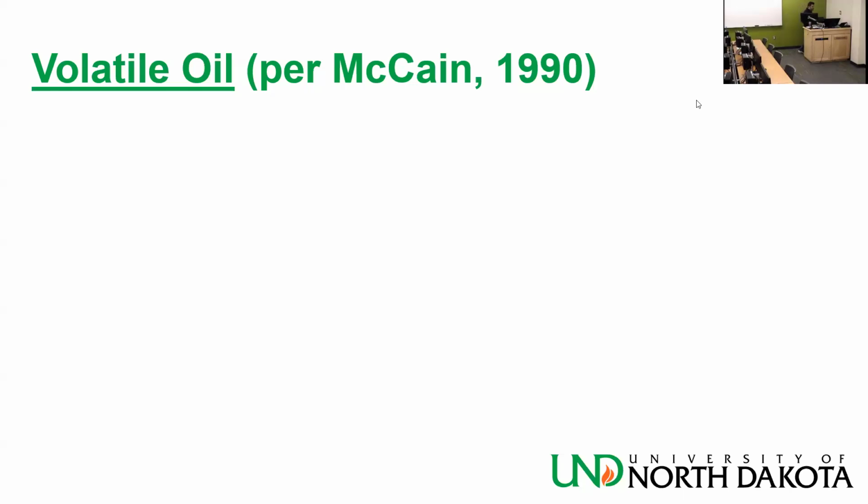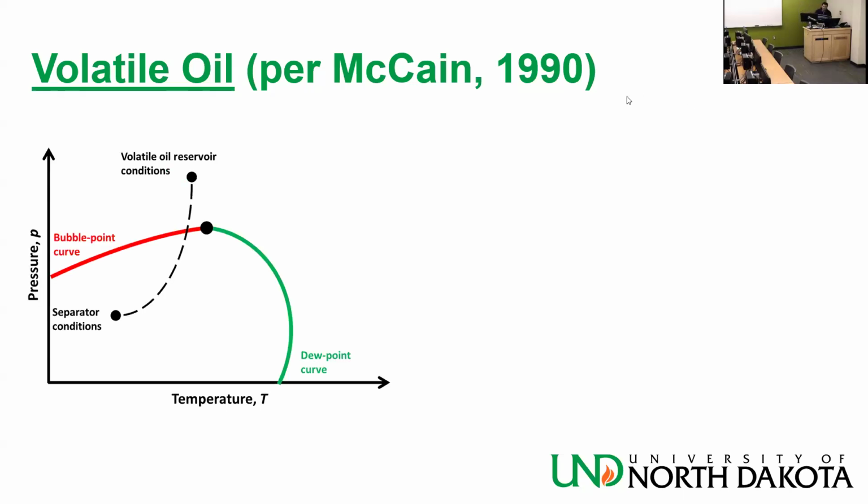So the phase envelope looks very similar to black oil, with a small difference that you may not catch unless you check it well, and that is the movement on the temperature is a little bit higher than before. We still lose a lot of pressure, but we also lose a lot of temperature. And the critical point and our line are closer to each other. So the critical point moved a little bit to the left.